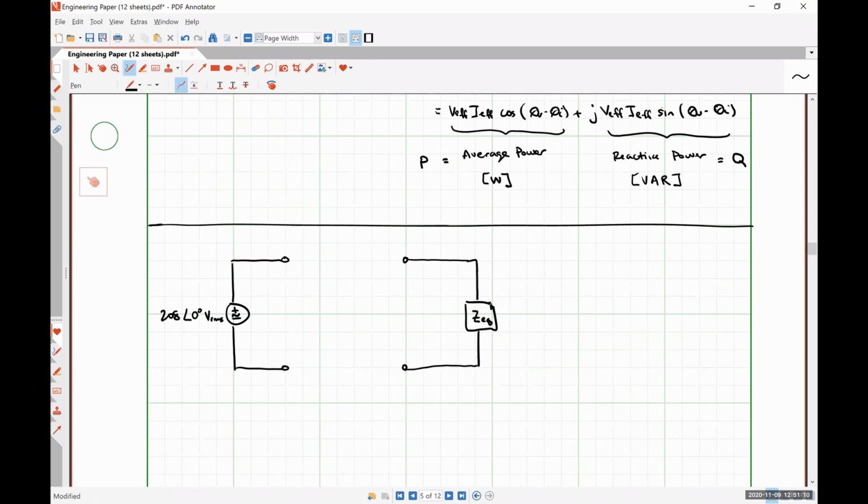But nowadays with modern smart TVs that are effectively a small computer inside of your television, all of those turning on the transistors and turning off the transistors is handled using direct current signals. So from the perspective of the transformer, your televisions, LED lights, all that kind of stuff are going to look like simple resistive loads. So let's say that this impedance ZEQ is going to be largely resistive. So let's call it on the order of 75 ohms real part. And there's also going to be some inductive loads.